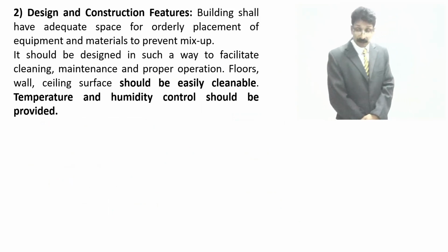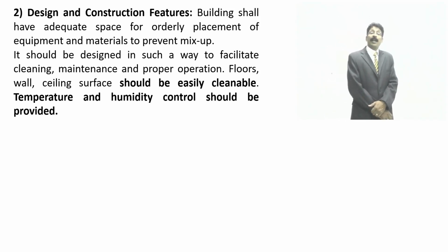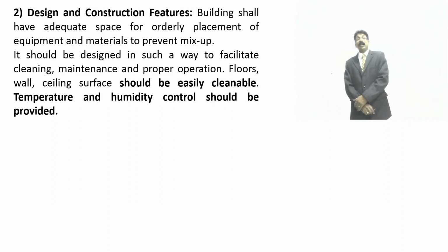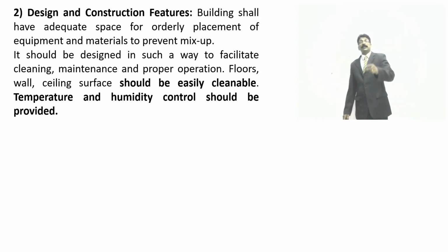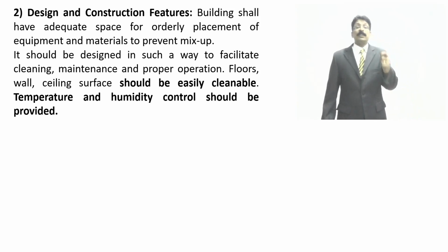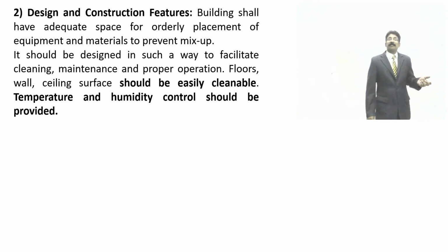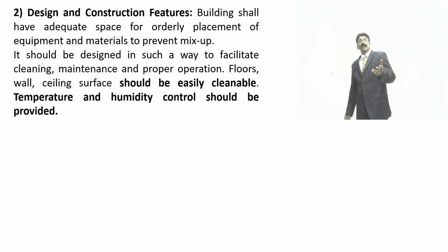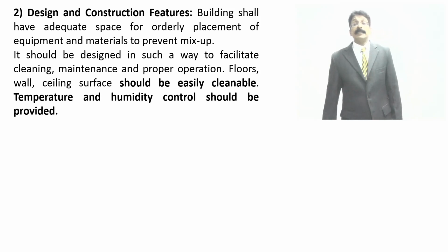What is the design? The building shall have adequate space and orderly placement of equipment and materials to prevent mix-up. It should be designed in such a way to facilitate cleaning, maintenance and proper operation. Floor, wall, ceiling, and surfaces should be easily cleanable. Temperature and humidity control should be provided.